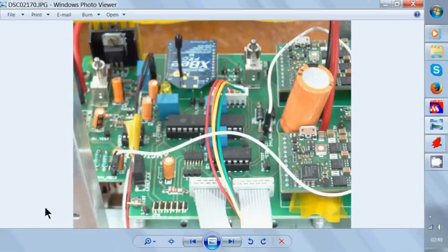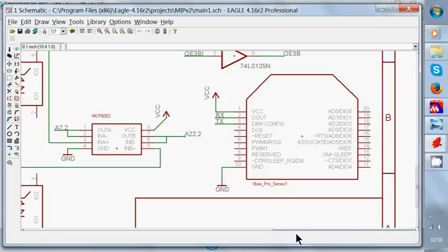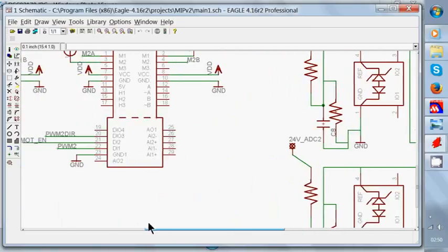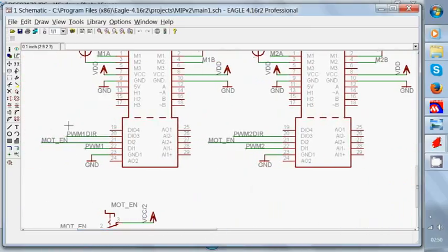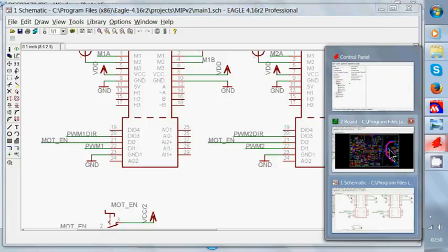So these are the two switches which are used to control the MIP. This switch is used to deliver power to all the processing circuitry, and this switch is a soft disable enable pin for the driver to avoid disconnecting the battery very often. This is used in order to disable the drivers and apply zero voltage across the motors, as shown here.